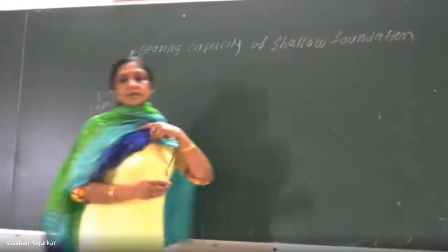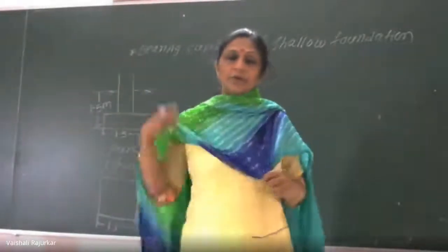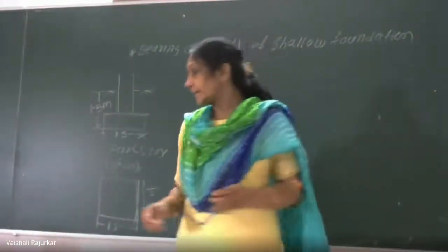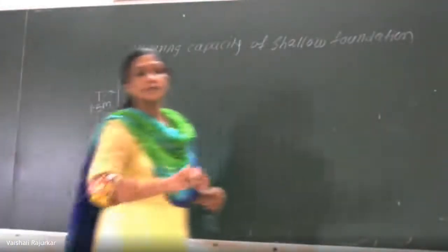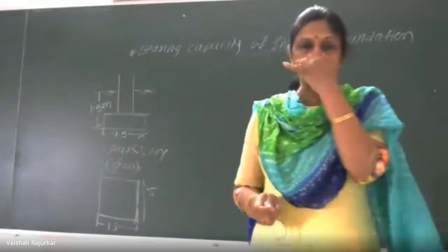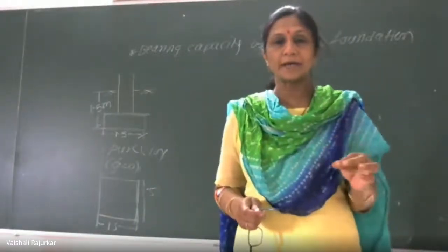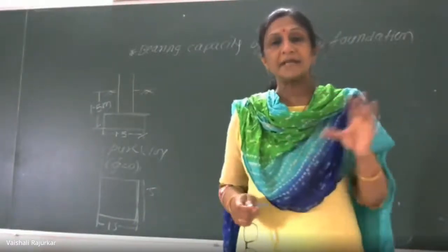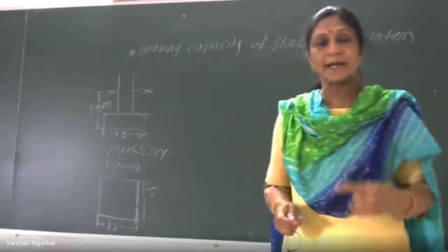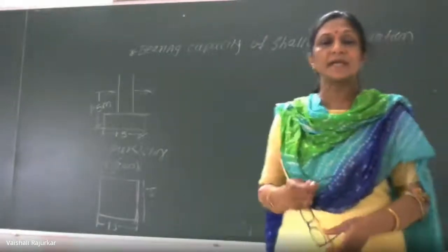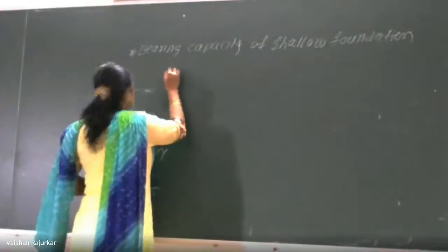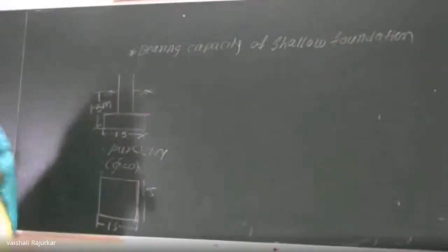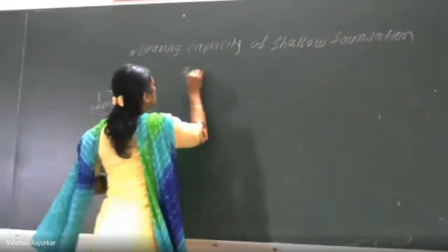First, nothing is mentioned about whether local shear failure or general shear failure is expected, because if the soil is a pure clay, by default phi is taken as 0, and if phi is 0, in that case Nc has to be taken as 5.7, Nq is 1, and N gamma is 0. So here, first, the footing is a square footing.